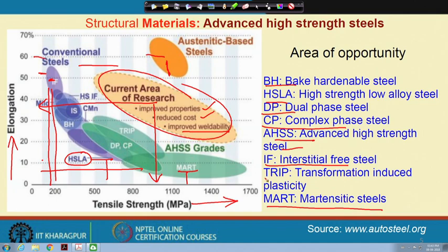Also, there is another category of steels at an advanced stage, called transformation induced plasticity. Here during deformation an austenite phase transforms into martensite. And there could also be twinning induced plasticity, and these steels are very well known for very high toughness, because they absorb very high energy before failure.